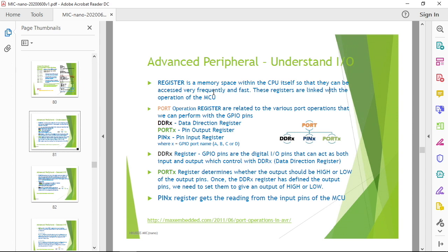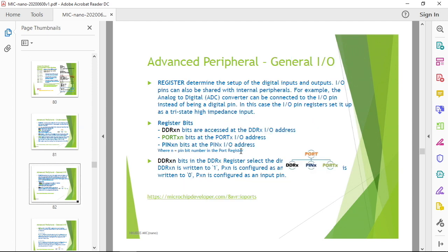In AVR or Arduino boards, most of the I/O can actually become output or input by setting some different internal registers. So you need to understand what they are. Okay, that can give you a full expression. But this is for byte form. Actually, we can configure the I/O pins of the port, some as output, some as input. So we need to get into detail for bit form.